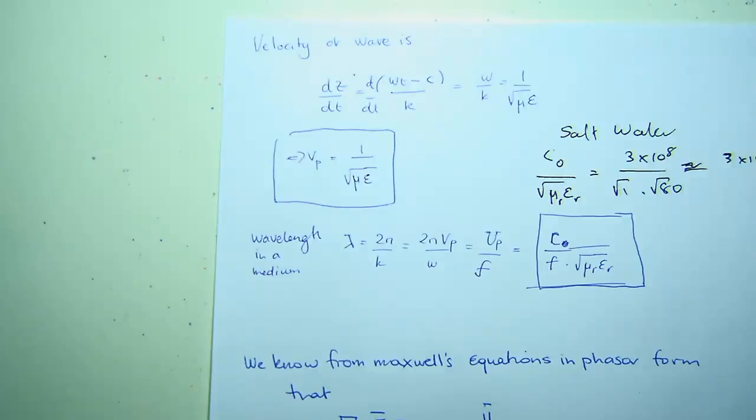So essentially all the passive components, like the inductors and all that, scale with wavelength, right? If you're building a transmission line and you want, for example, a quarter wavelength transformer, and we'll go through this in greater detail, what it means is if the material has a higher dielectric constant, all those components will be smaller. For example, at 2.4 gig, the wavelength, if I'm doing it correctly, is about 12 centimeters. If you wanted half a wavelength on a PCB board, that's 6 centimeters.